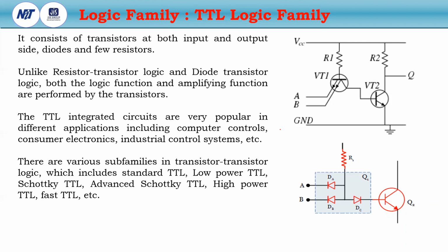In the RTL or the DTL, the output transistors just act as a logic function. But here the output transistors also amplify the output. The TTL integrated circuits are very popular in different applications, including computer controls, consumer electronics, and industrial control systems.